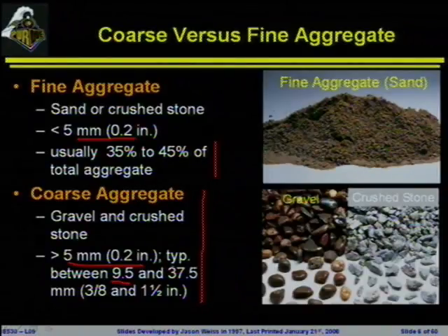In the late 1980s, early 1990s, all the rage was to make the aggregates smaller. Smaller aggregates, smaller aggregates, smaller aggregates. Any guesses why we wanted to make them smaller? Guys who own crushing plants were really good salesmen. More homogeneous. And as the drive was to increase strength, the more homogeneous the aggregates are, the higher the strength typically is. So the smaller the aggregates, the strength of the concrete typically goes up.